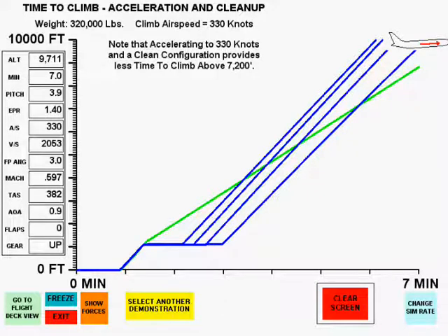The most important thing to note from these curves is that the break-even altitudes for time are much lower than normal jet cruise altitudes. This means that the most efficient climb to cruise altitude is accomplished by retracting flaps and accelerating to the desired climb airspeed as soon as possible after all obstructions have been cleared. This is the opposite result found for break-even altitude for distance cases, where it was better to clear close-in obstacles before acceleration and configuration cleanup.